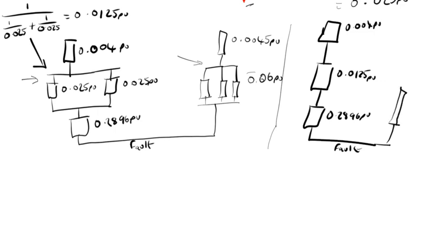And also from before you'd have a substation 0.0045 pu. And then using series technique, so it's basically this value plus this value here plus this value, and then this value here plus this value here, you'll end up with two simple resistors, 0.0361, and then one here, 0.0227. These are PUs.